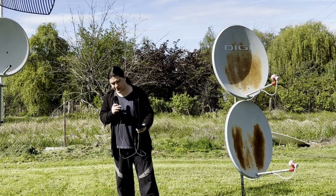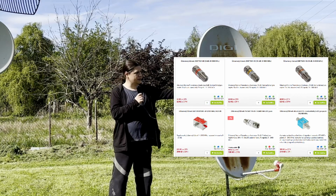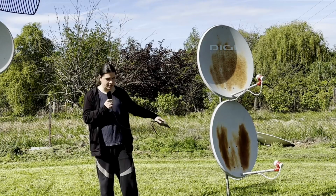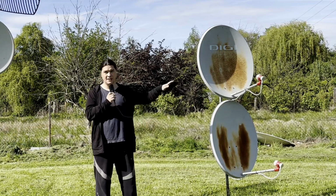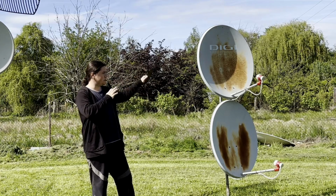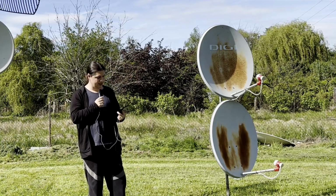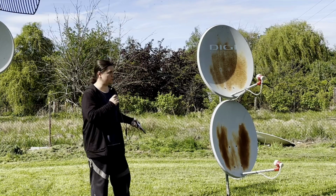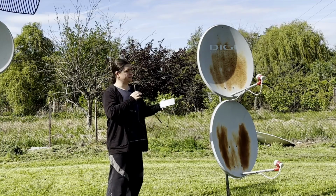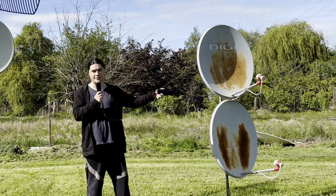If you want to stay on the safer side, you may want to consider buying an attenuator to put between your SDR and the cable that's going to be feeding it from the LNB, because the conversion gain of the LNB is usually very high. It's meant to push all of that signal through a lot of very lossy cable. I personally don't use it. I don't want to give an example that it's okay to do that. It's probably safer to use one, I don't know, put like a 5, or it's probably not enough, 10 to 20 dB attenuator. I do think I have a 16 dB attenuator and I use it sometimes.